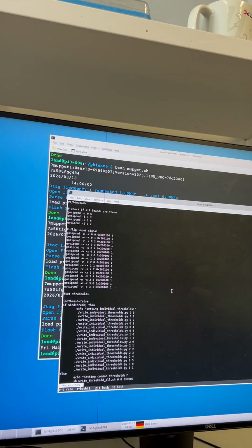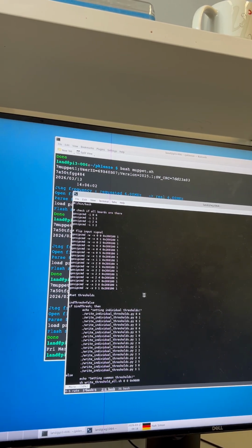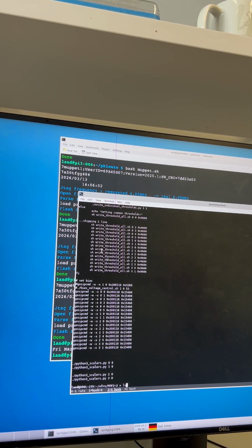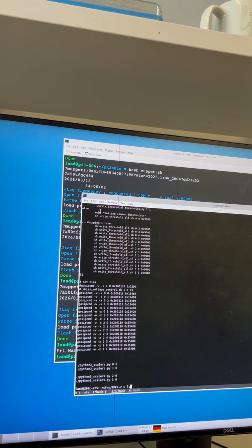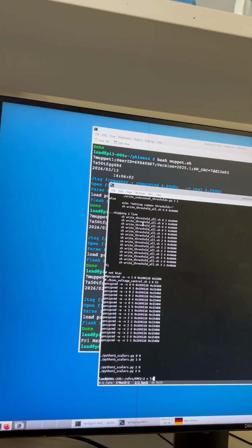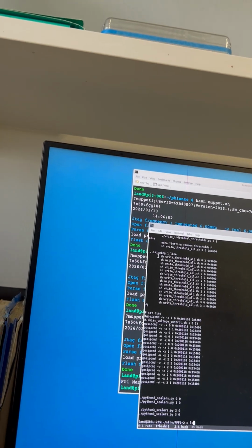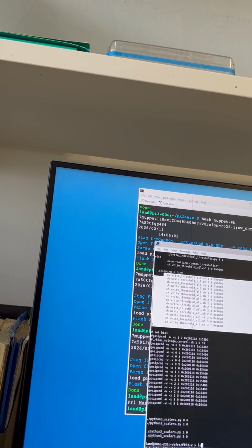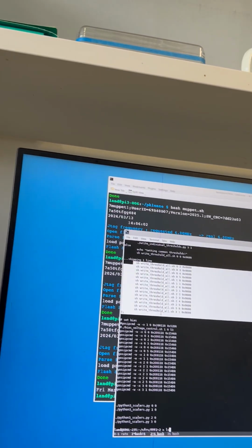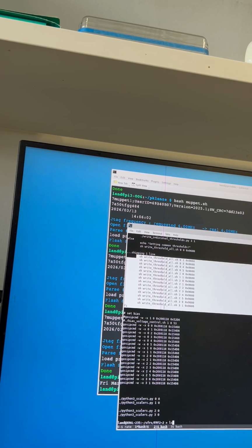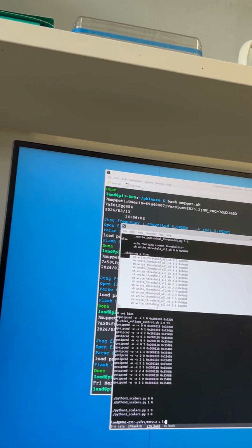And then we have to set the thresholds. For the thresholds I have 2 methods. We have either individual thresholds, so every channel gets 1 value, or we have a common threshold. At the moment I'm working with a common threshold, and you see that here we are writing the same threshold value to all boards. But later on we need to specify. We will write 128 thresholds per board, one for each channel.